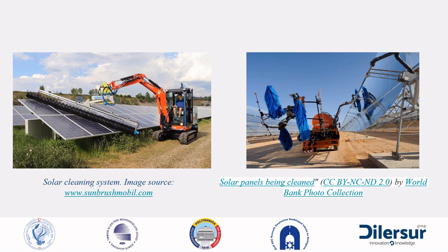If water is used to clear the snow away, it must be lukewarm. Hot water should never be used for clearing snow off the panels. Solar panels are made of tempered glass, and the extreme temperature difference between hot water and cold panels can crack them. Never use a pressure washer on solar panels. Although the glass is quite durable, they are not designed to be hit with high-pressure water jets. All necessary work safety measures must be taken.